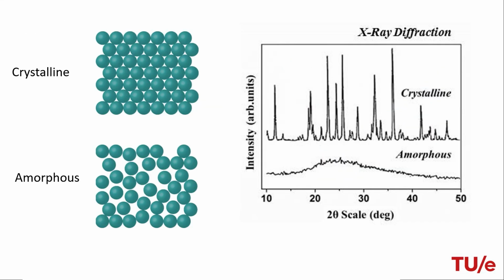It is mentioned that XRD works for materials that are crystalline in nature. This is so that uniform interference patterns can be detected to allow for usable data to be extracted for analysis, as seen on the top. In contrast, amorphous materials have an irregular arrangement of atoms and do not lead to material-specific interference patterns.